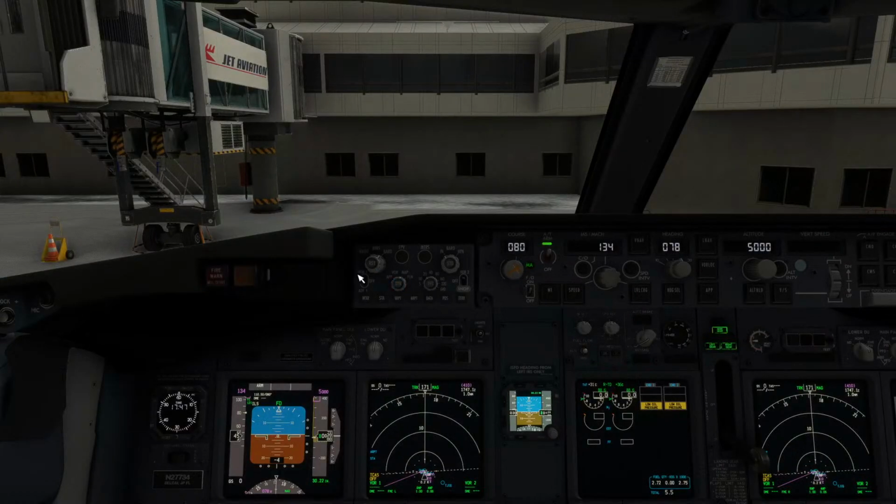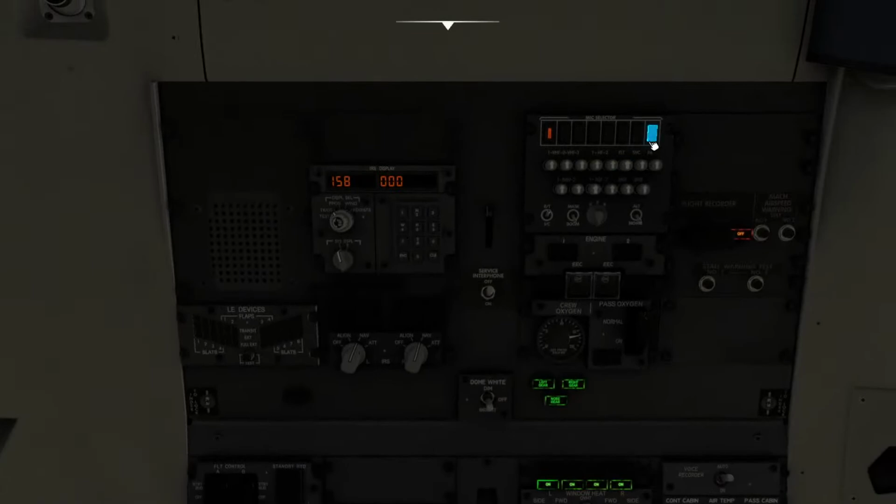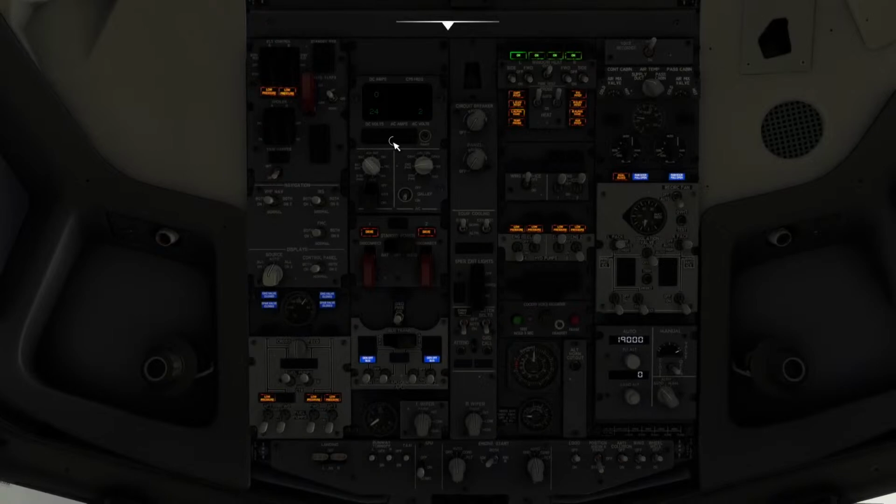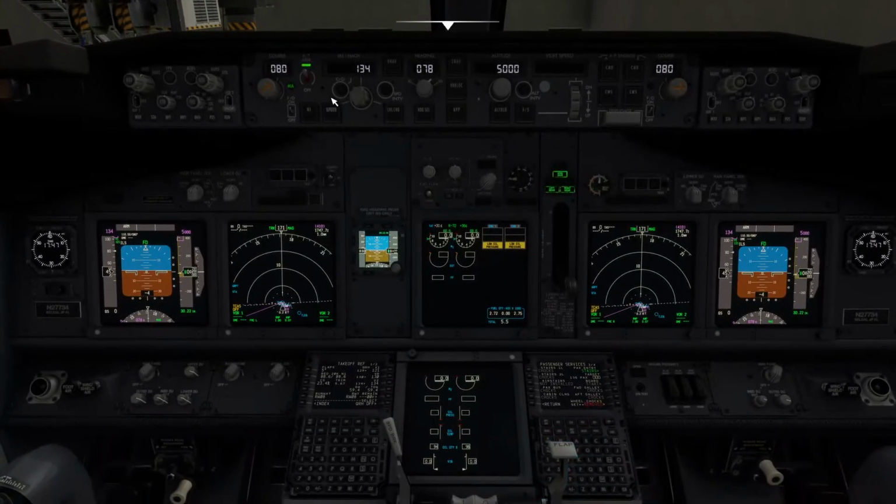I'm going to leave the airplane ready for pushback and start, and then we are going to read the training scenario instructions. So I'm just going to do a couple of things here that we need to prepare for pushback and start. This is the normal flow on the 737. So first flight of the day, we go to the right igniter, and yep, everything looks normal here. I'm going to use LNAV and VNAV for this departure.